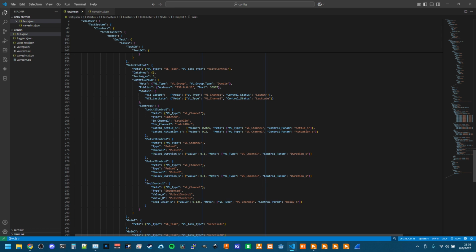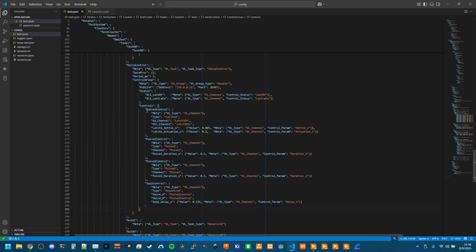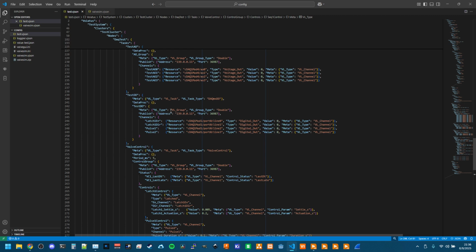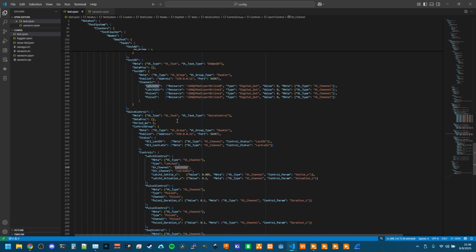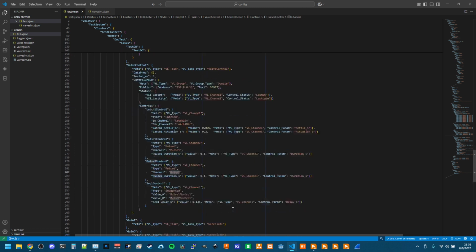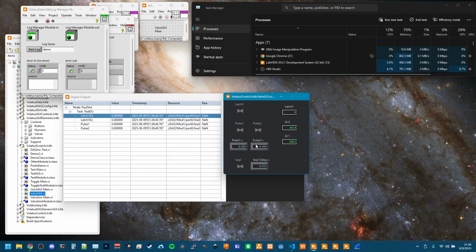So there's this valve control module that's been configured to run. It's got 4 different bits of logic that it's running with the configuration that's all in here that link the valves to each other and to the digital outputs that they're controlling. So like latch 1 enable, we can see is this guy here, and there's latch 1 direction, and pulse 1 and pulse 2. And then some default startup values, such as these 0.1s that we can see here in this GUI.